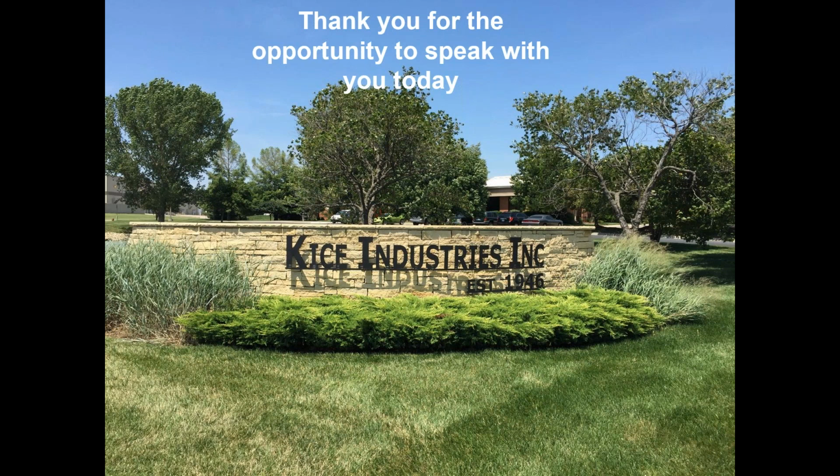Too low of an air-to-cloth, I would love to be able to convince everybody that a 1-to-1 air-to-cloth ratio is the perfect filter to buy every time. Now, if you buy that filter, you probably will never have to change the filters, but you're going to have a big, big filter for maybe a small process. So the danger in a low air-to-cloth isn't necessarily with function.